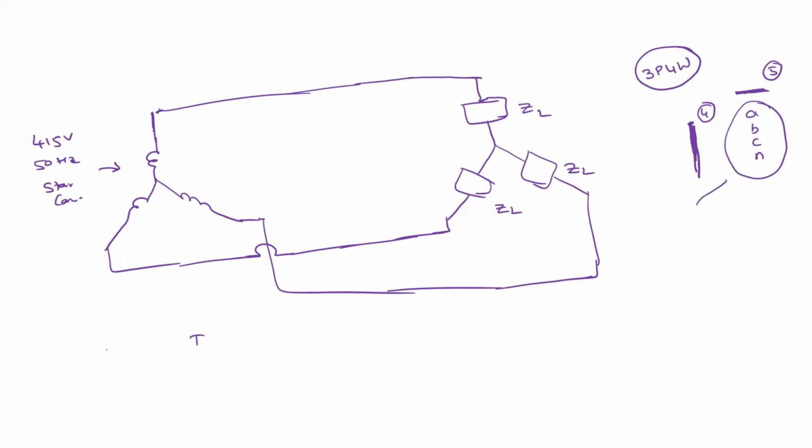This is for connecting 3-phase loads and single phase loads. For example, in your vicinity, some small scale industry is there. For industry, they require 3-phase, so they directly give the 3-phase supply by using A phase, B phase, C phase, and neutral. For domestic application, for your home, how will they give that? A phase here and neutral. That is how they will go.